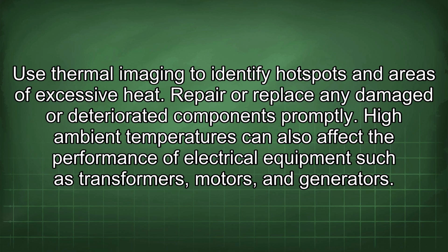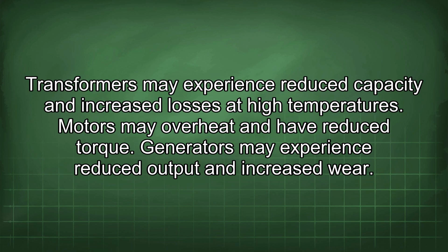High ambient temperatures can also affect the performance of electrical equipment such as transformers, motors, and generators. Transformers may experience reduced capacity and increased losses at high temperatures. Motors may overheat and have reduced torque. Generators may experience reduced output and increased wear.